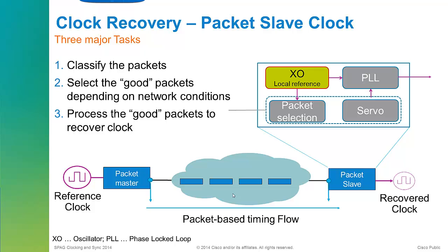Just covering packet-based clock recovery. I touched on this a little bit previously, but as we said before, there's a clock recovery process where a device needs to recover the clock and condition its local oscillator to be in tune with the incoming frequency reference. In a packet-based network, you don't have that frequency reference. You're relying on these packets arriving and trying to figure it out.